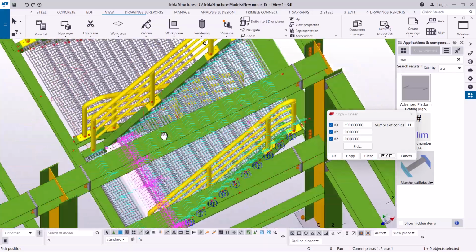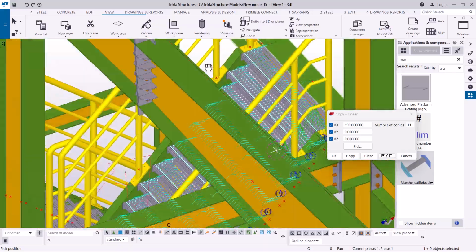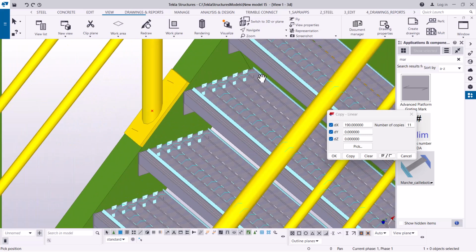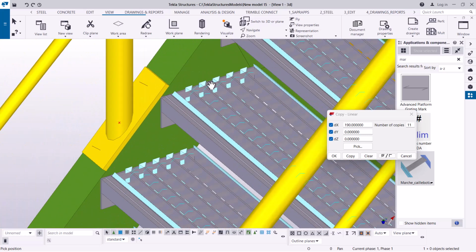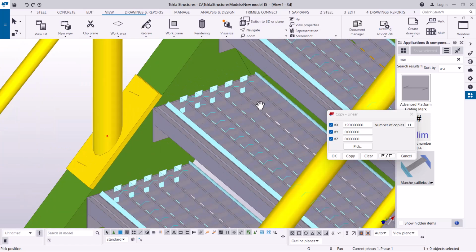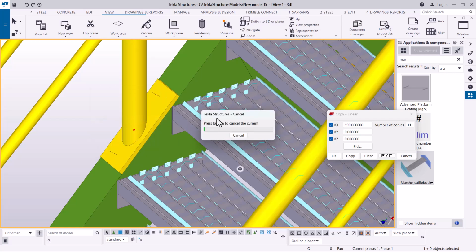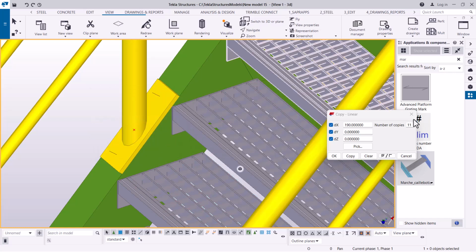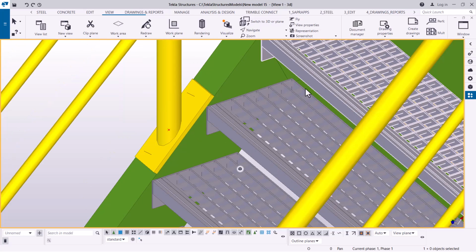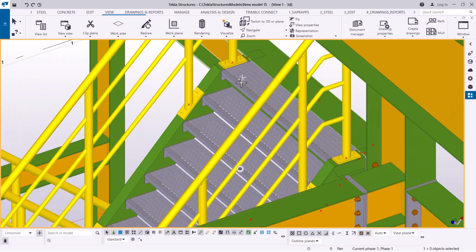But if I turn it around, you can see so many symbols of weld. So I want just to get rid of the symbols you see, like the ticks or rods, or welding rod holder here. You can see it looks like that. So let me just right click and click interrupt just to walk out of that command. Then I'll left click by left clicking on empty screen. So if you see this orange thing, means you've left clicked. So I'll right click and come to redraw. So if I redraw, I'll lose all those symbols. So our model will look as nice as it is, as you can see here.